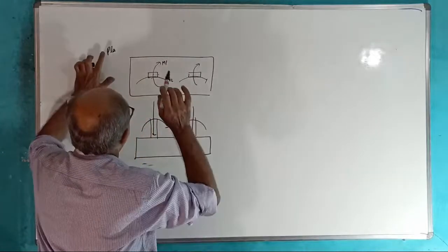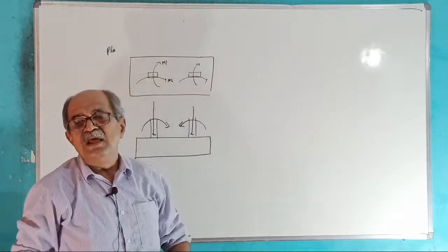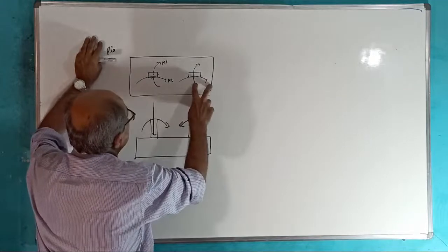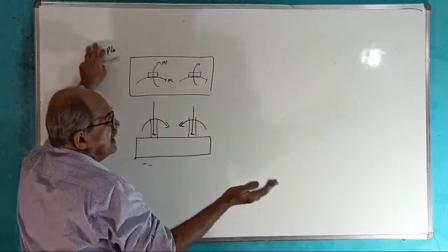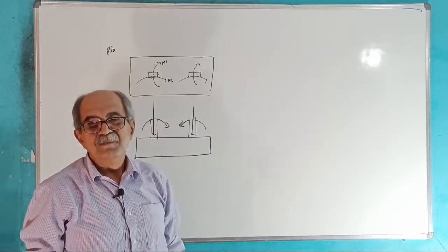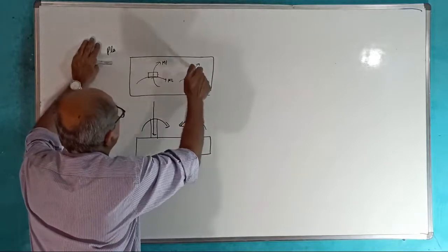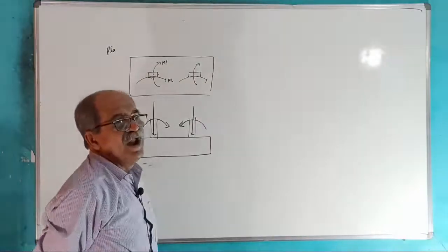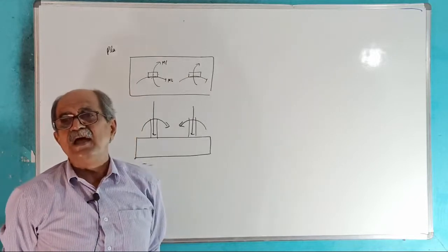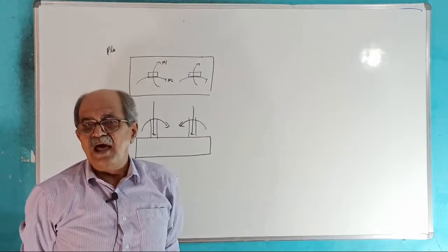Now, when you study engineering, at that time a theory is given for combined footing: you provide the projection in such a way that the pressure is uniform. That is fully bogus. Why? Because practically the column load will keep on changing. For dead load and live load, one column load will come. If you consider dead load plus live load plus earthquake, one more load will come. Or if you consider dead load plus earthquake, another load will come.